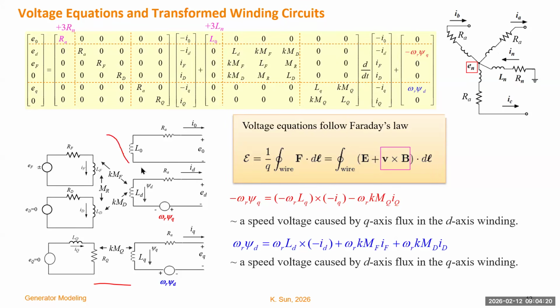The zero sequence circuit is only useful under unbalanced conditions. For steady state and balanced conditions, usually the current will be zero, so we can ignore this circuit for most of the rest of this course. Later, if we talk about fault current analysis or short circuit study, we can bring this circuit back.